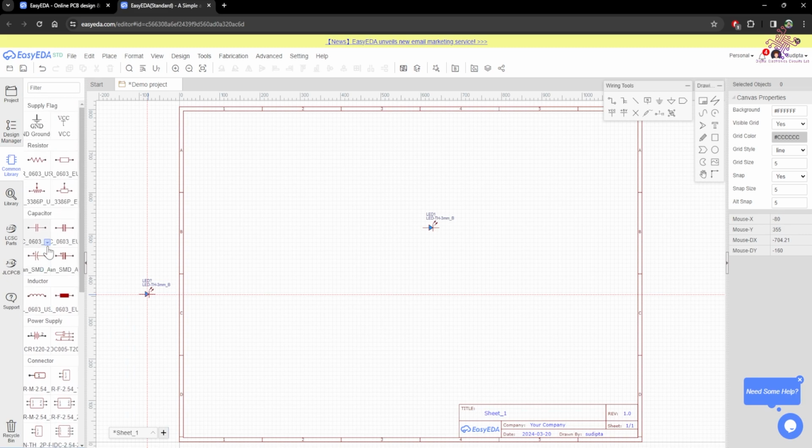So next I want to add a resistor. That also I want to add the through hole type. So just click on this arrow and then you have to select the type of resistor. So different types, different sizes of resistors are available. So a resistor with 0.4 mm axial resistor I want to add here. By selecting it, I have to place it on the workspace.